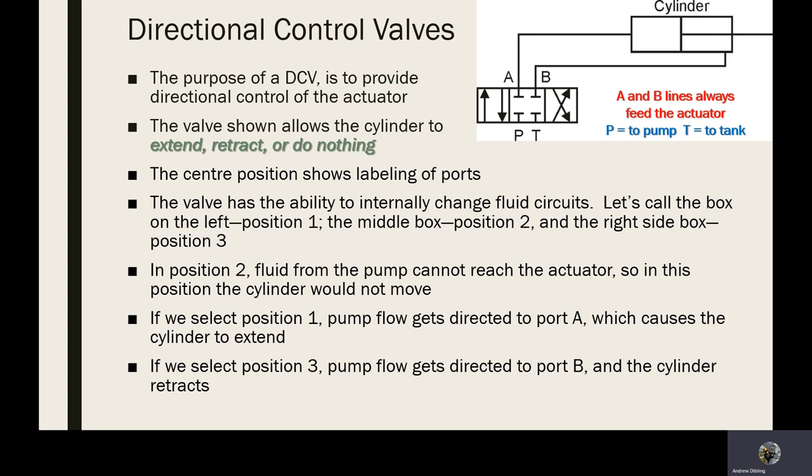Right now, what happens is when it's in one position, it goes from P to A, fills up the back of the cylinder, drives it this way. And the other is going from B to tank, so the fluid is pushed out of this side of the cylinder and back to the tank. When I engage this, the pressure goes into B and drives the cylinder this way. The A will then take that and take it back to the tank.